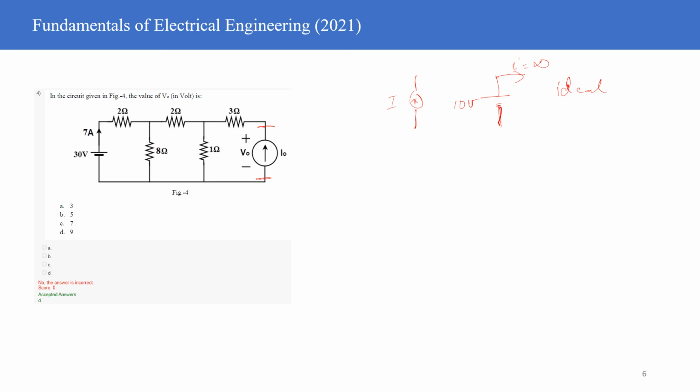Practically, you can have a limitation, where the battery can give you 10 ampere at 10 volt, which is the rating of the battery. After this, there will be a dip in the voltage, so the voltage will dip to 9.8 at 11 ampere, let's suppose. But for an ideal battery, there is no such limitation. You can have any value of current: 10 volt, 10 amperes, 100 ampere, or any X ampere.